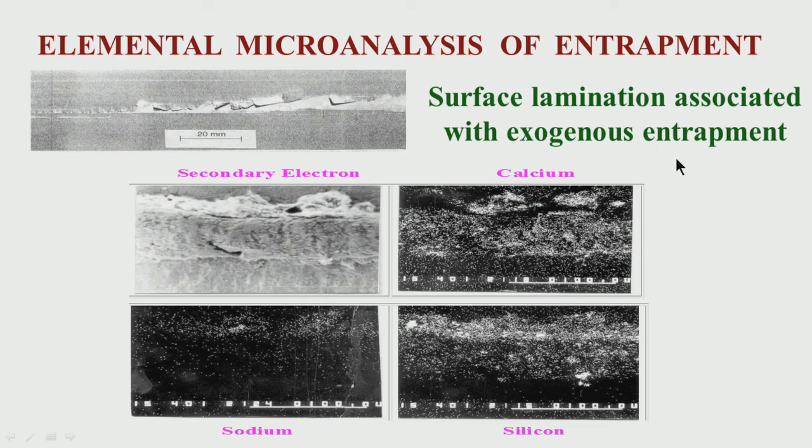This is possible by cutting a small sample and putting it under a scanning electron microscope which has EDX or WDX. So, we know from the elements present what are the possible sources. If you know the sources, we know what went wrong. This is of course post-mortem.